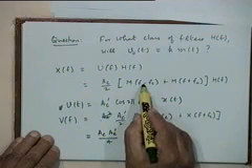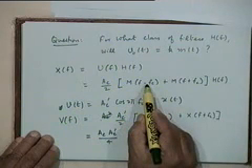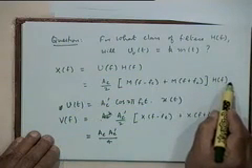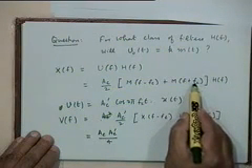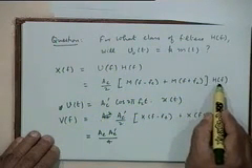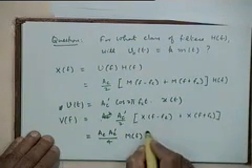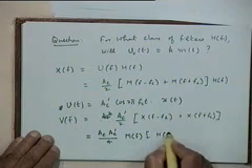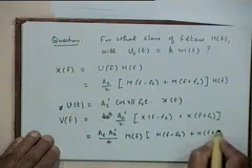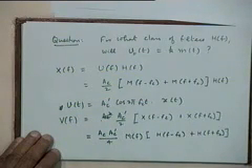when this becomes, so if I shift it by plus fc, you will get M(f), and that will become H(f plus fc). Similarly from here, if I shift it by minus fc, I will get M(f) into H(f minus fc). So M of f will be common in these 2 terms, and this will be H of f minus fc plus H of f plus fc. Is that clear? These 2 terms?